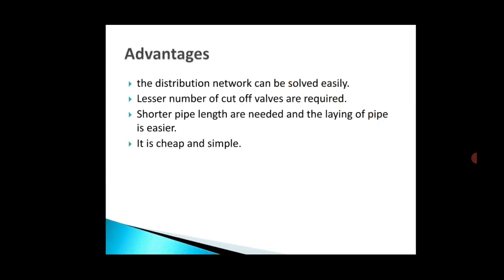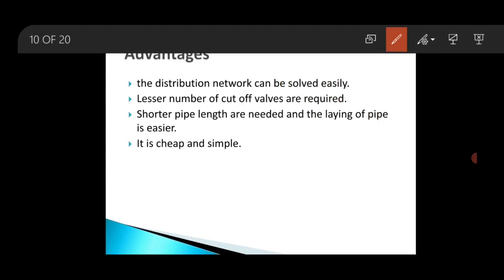Okay. So what are the advantages of this system? The distribution network can be solved easily and it is possible to easily and accurately calculate the discharges and pressure at different points in the system. Then here a lesser number of cut-off valves are required.